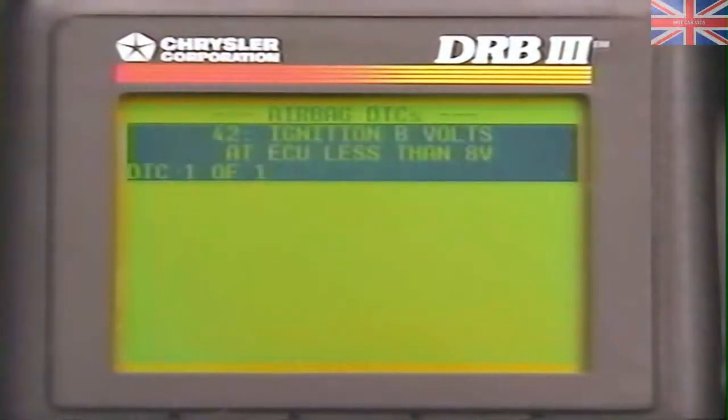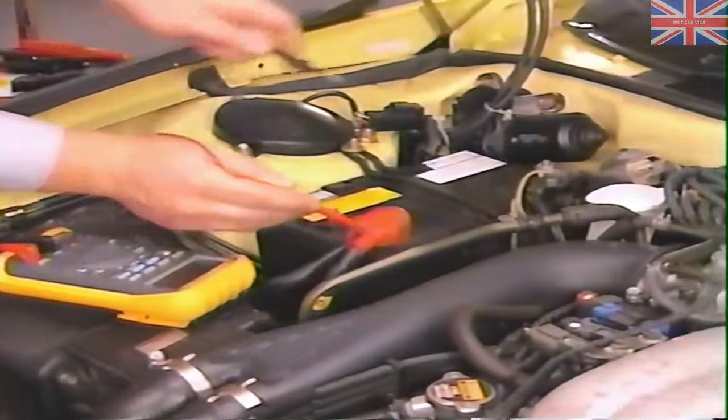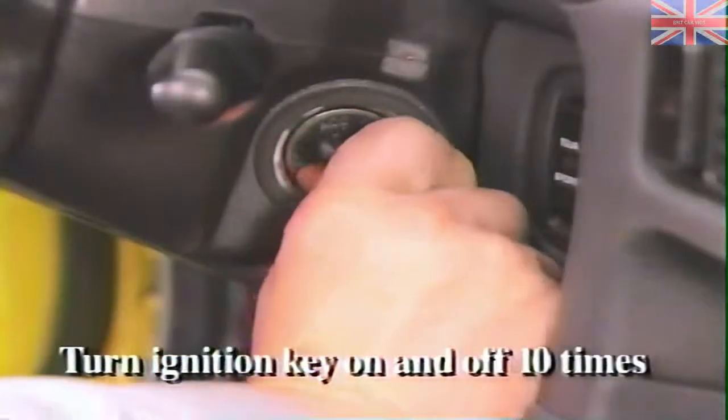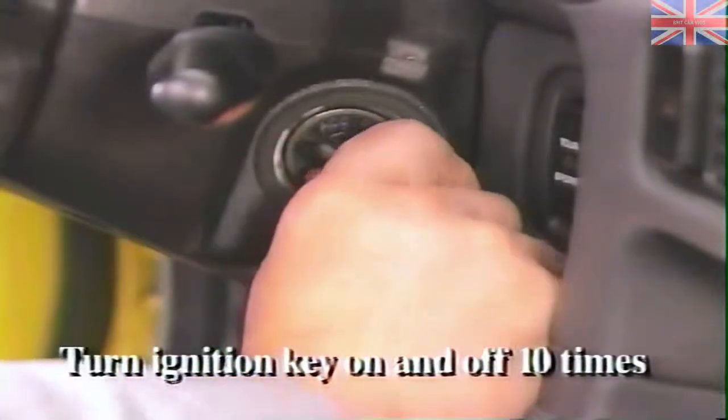So, if one of these codes is displayed, you should start by checking battery voltage. If the battery is not fully charged, recharge it or replace it if necessary. When you have a fully charged battery, check the warning light. If the light is on, turn the ignition key on and off 10 times and check the light again.